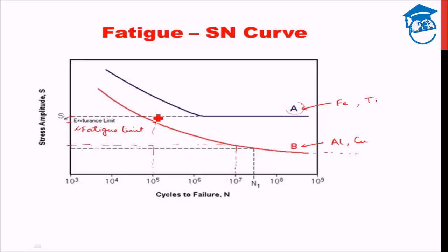But for materials which do not have a fatigue limit, we do not have that option. We need to keep monitoring the status of the component. Also we need to do studies and find out how many cycles the material is safe to operate till. This essentially gives you an idea about the number of cycles a component should be exposed to before it needs some maintenance or needs to be changed.